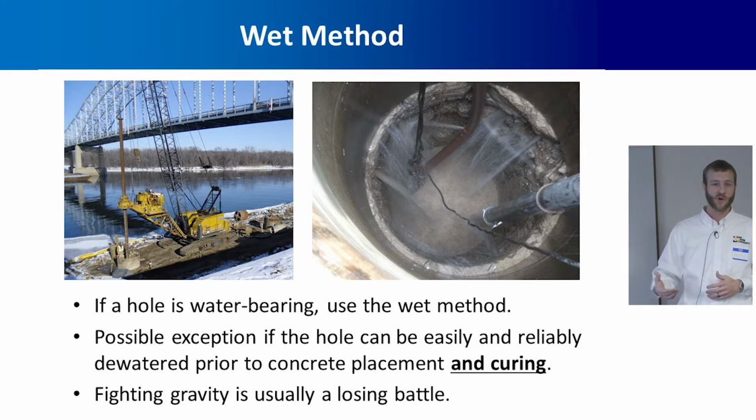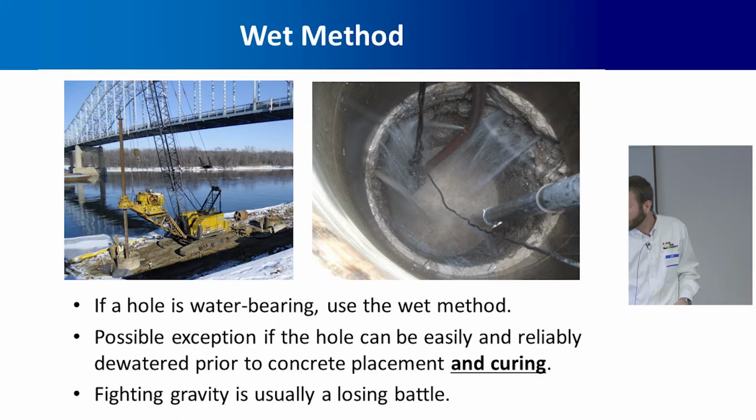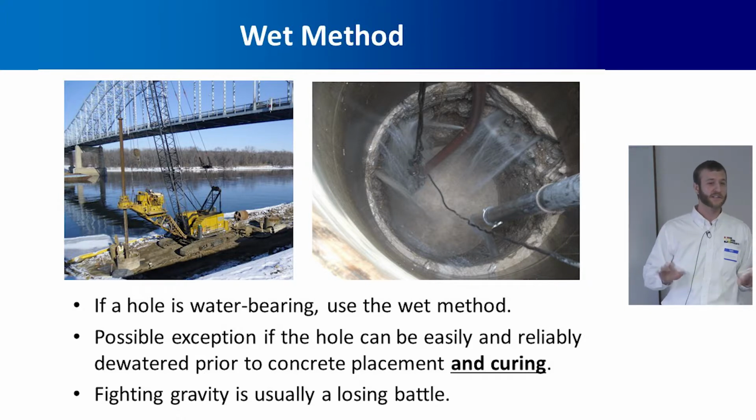And even if you could keep it dry enough to drill it in the dry, you've got to make sure that when your concrete is being placed and curing, you're not having groundwater try to flow in there, which can cause problems with the concrete. So the bottom line is fighting gravity is usually a losing battle.